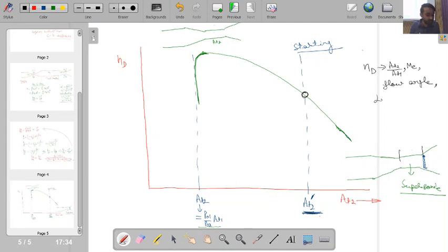The last important parameter is the length of the second throat. Okay, so from practical considerations, all these parameters are to be adjusted so that we can avoid the initial transient operation, and also operate the diffuser with maximum possible efficiency.